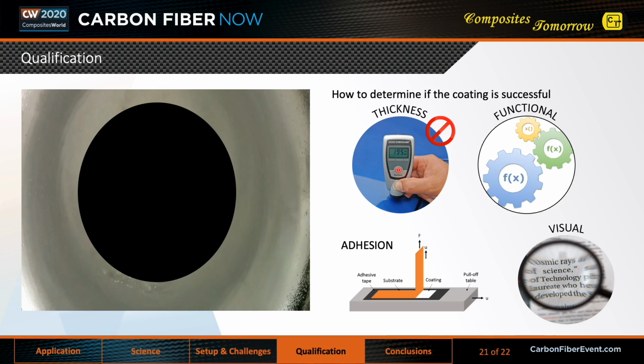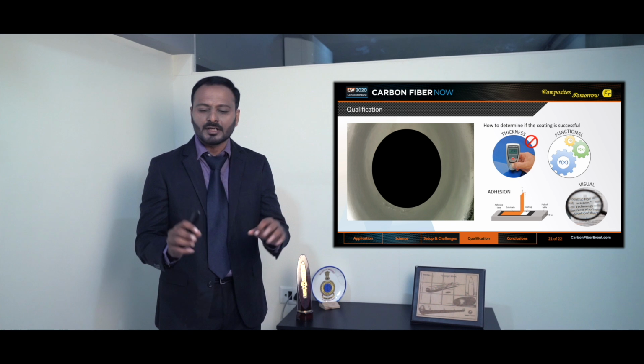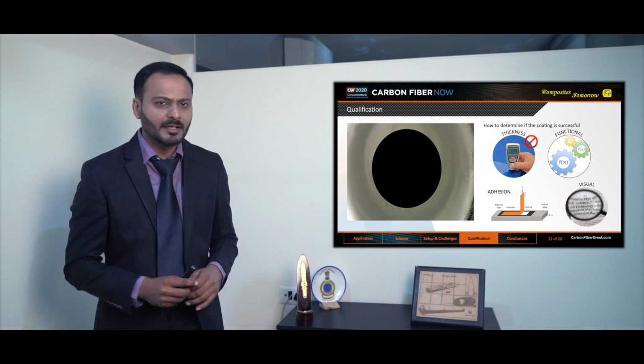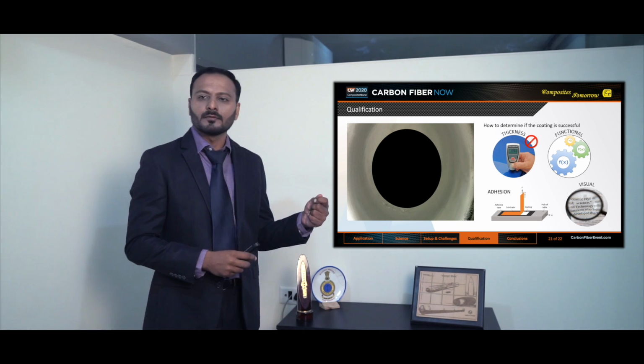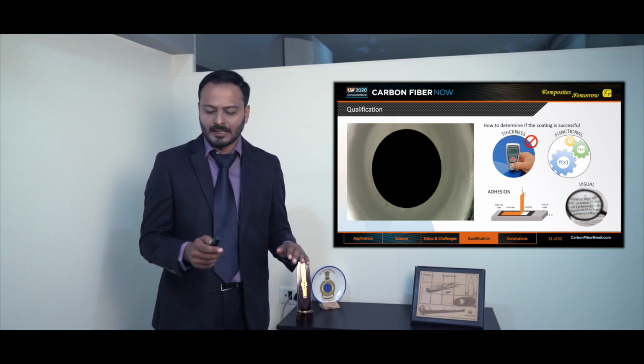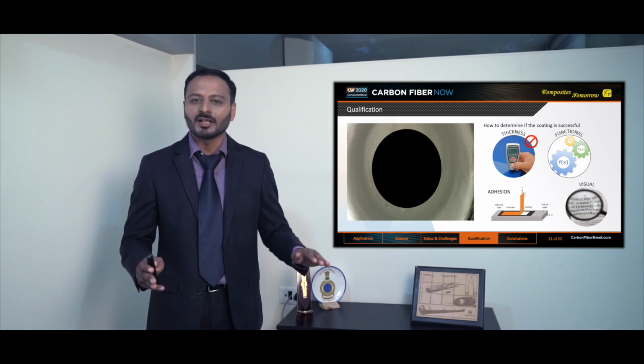And at the end, one must try and do an adhesion check. A simple adhesion check, put a tape with a standard tackiness and adhesive bonding and try to pull it off. The coating should not come off with the tape. And that's it. Your sputtered shell is good to go.